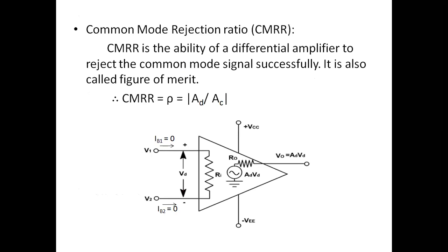Now, we are supposed to study about the parameters which we are using in the differential amplifier, like CMRR. You can call this the common mode rejection ratio. I have drawn the same diagram. What we are doing here is giving one non-inverting input and one inverting input. We are giving the power supply to pin numbers 4 and 7. We are taking the output here.